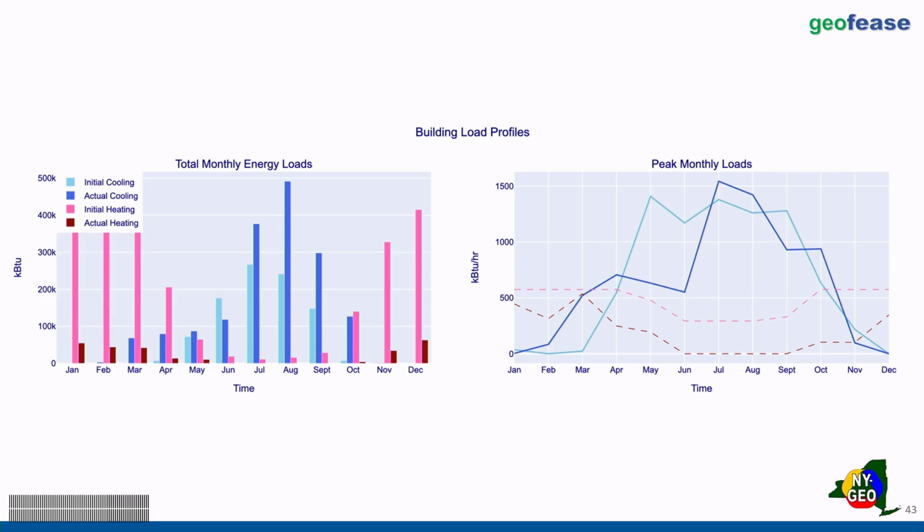This illustrates the differences between 8760 energy models and actual performance, and it changes, right? It's a dynamic thing, so month by month, these loads change, and we have been seeing quite a bit of deviation between the 8760 hourly energy model that's used for design and the actual loads that are put upon these ground heat exchanger systems. I think Isabel mentioned they're seeing that at Eversource right now, and maybe that's because of some auxiliary usage that wasn't intended in the original design, but we are seeing quite a bit of difference from the theoretical model that was used in the design phase to the actual